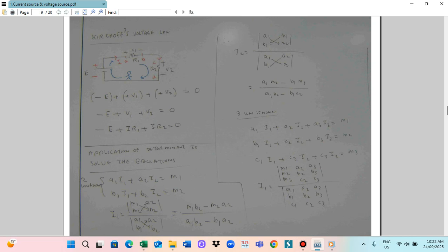Okay, you have to put the positive and negative signs. On the battery, the longer terminal represents positive and the shorter terminal represents negative. When the current flows, one end is positive and the other is negative. Similarly for resistor R1 and resistor R2, the current flows in through the positive end and out through the negative end. In this way you can label the points A, B, C, D.